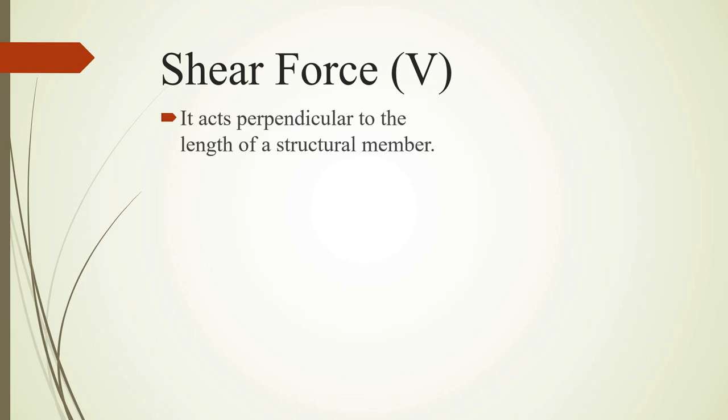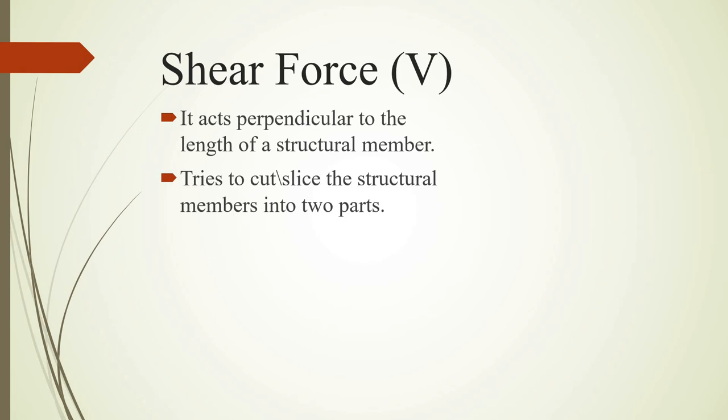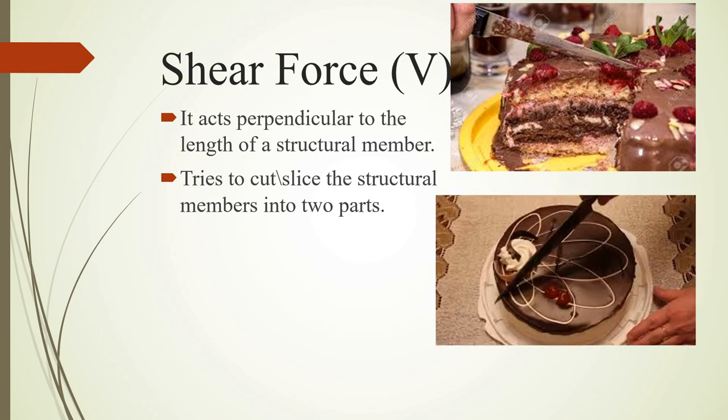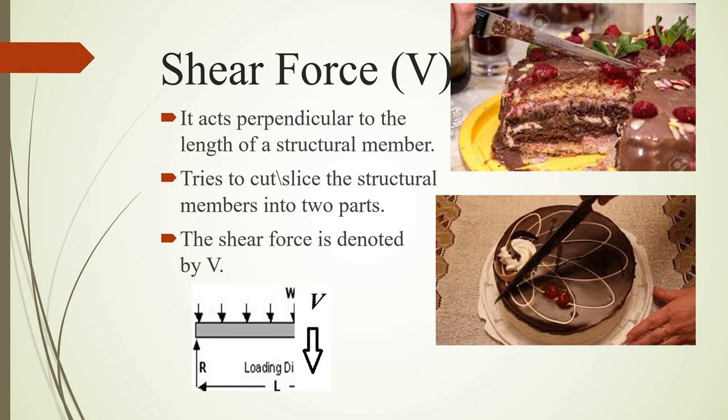Now shear force. It acts perpendicular to the length of the member. It tries to cut or slice the structural members into two parts. I always use the example of a cake. You cut it or you slice it, so you're actually shearing off the cake slices. And this is again cutting or shearing of a cake. Now this force is denoted by V, and this is how it looks. So it's the perpendicular one.